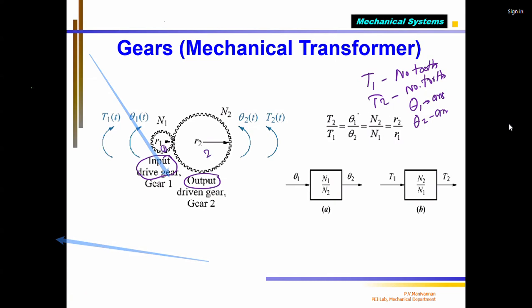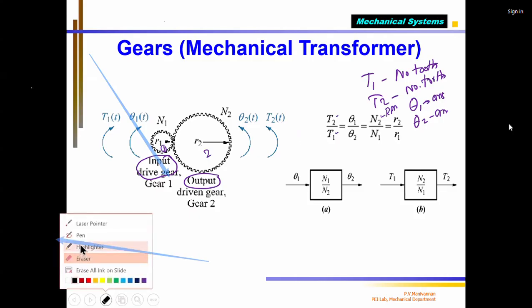So the subscript says that T2 means the number of teeth in the secondary or output gear divided by the input, and N2 is this RPM. The TR can be written, not TR, it is a GR, extremely sorry, it is GR.